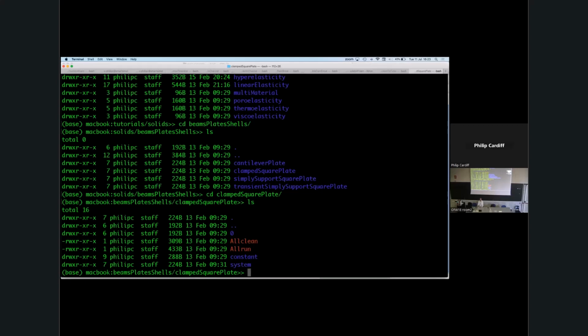Same for beams, but there is actually a beam solver. There's a talk by Željko Tukovic and Shivani Vali, who's a PhD student. They've worked on a finite volume based beam solver in OpenFOAM, which is a true non-linear geometric beam. So if you need a beam, that doesn't help you for an airfoil, but essentially, yes, it can be done. It's just nobody's done it. So yes, doing a 3D approach probably wouldn't be efficient.